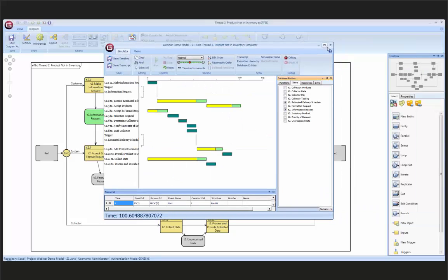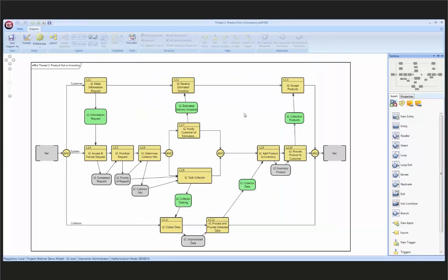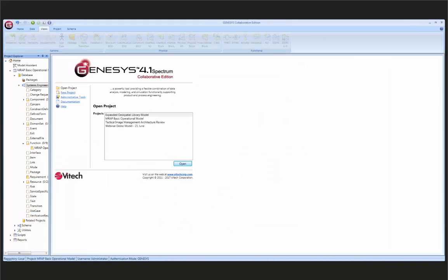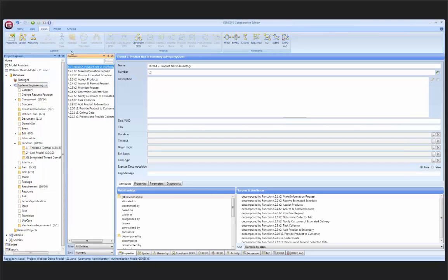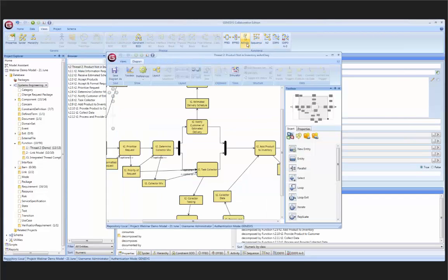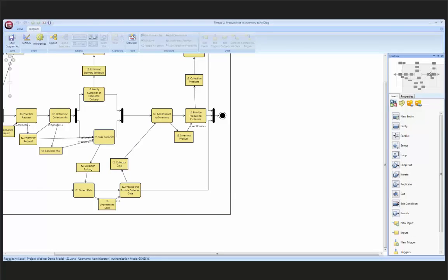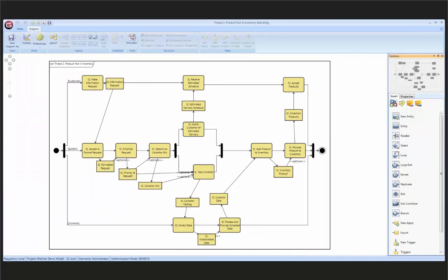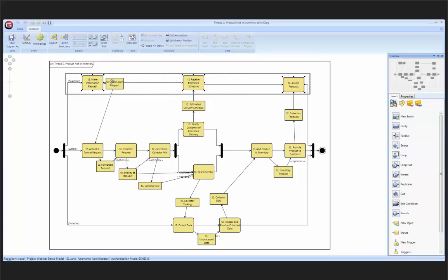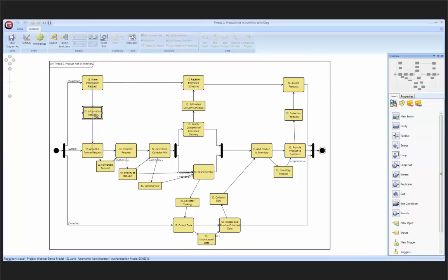So this is troubleshooting our functional models, making sure that those models are validated. They actually do what we wanted them to do, and the functionality is there. Now, this is the EFFBD. Real quickly here before I leave this, let's go back to my model here, and I want to show you. This is the thread. This is the activity diagram for this. It's synonymous with, or it's the same as, the information you see on the EFFBD. It's just shown in a different notation.